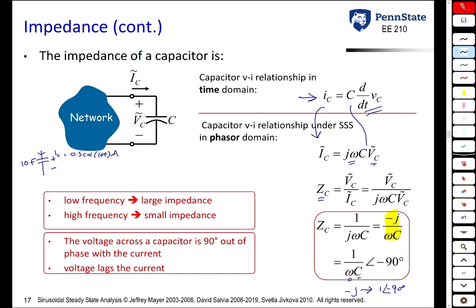The voltage is going to be the integral of the current divided by the capacitance. When you integrate the cosine, you're going to get a sine. You're going to divide by the 10. You're also going to divide by another 10 because of the capacitor value. And so the voltage is going to be 0.005 sine 10t volts.